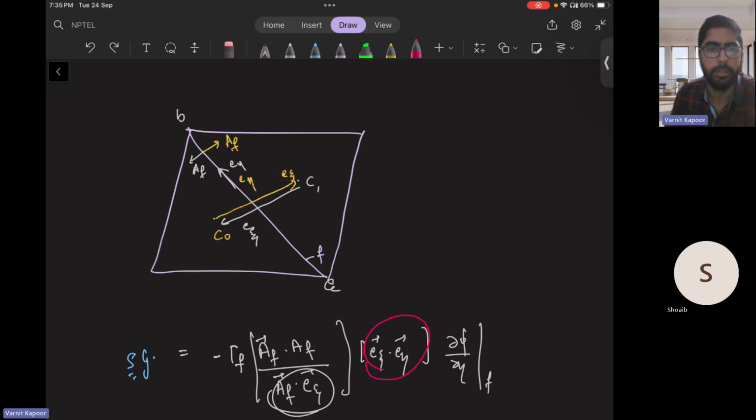That is it. So we have a list of all the faces in a mesh. The cell numbers of these faces are also known. We have a list of cells in a mesh. We calculate A and B for cells by visiting all the faces. Then visiting each cell and calculating the AP. Then we calculate, visiting each cell, the source term contribution as it follows. And of course, the secondary gradient needs a gradient calculation at cell centroids. Then the equation has to be modified to incorporate the boundary cells as well. It's just so far for the internal cells.